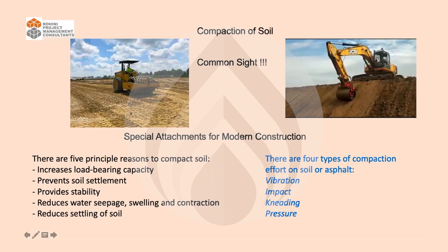The first one you can see is a vibro attachment, so it will impart more vibrations and you will get a better rolling effect. The second one, what you see, this is for rolling on an inclined surface, right? This is actually a JCB, and this is just an attachment. In lieu of a bucket, you can use this attachment. So this is for canals, canal lining. A lot of things you can use this for. Obviously, your work would be faster and of better quality, right?